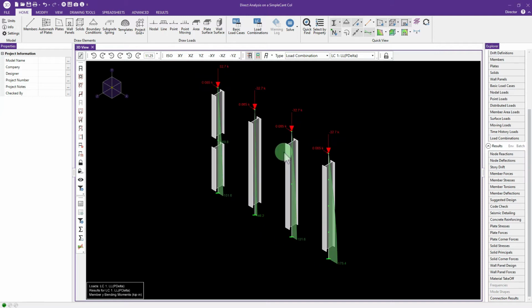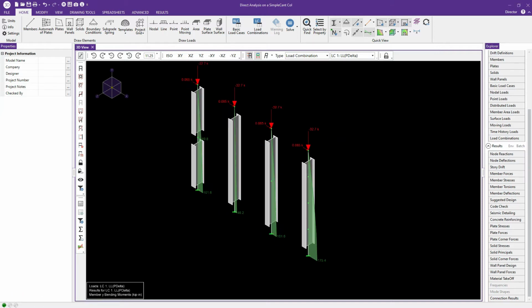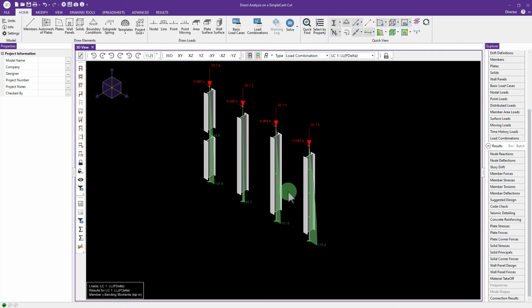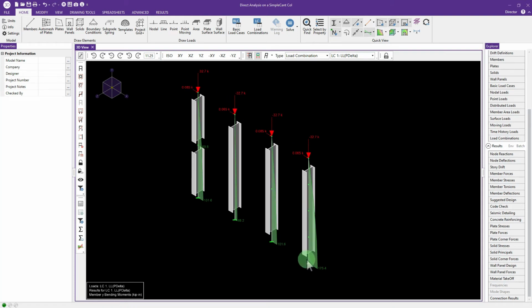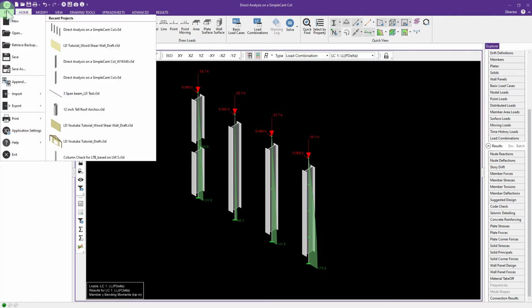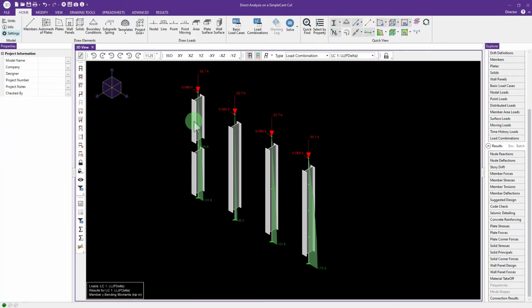Right off the bat, you know that making your model into more discrete points, or breaking it down to discrete points using nodal shear, gives you different values. And the more you break it up, the more correct the analysis is. In this case, using nodal shear, you have to break it into something like, I believe, 8 or 16 elements. It's a lot.